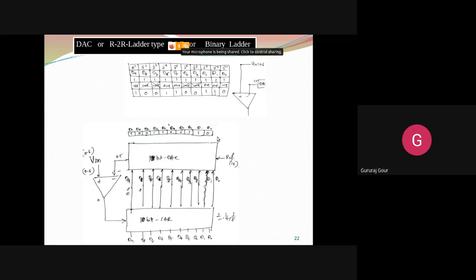Okay. So only this much will be given in the exam, to let you design the ADC and get it converted to analog. So let us see the steps here. So the weights I have written here from left to right for a 10 bit ADC, from D9 to D0. You need to draw the table. Right, D9, D8, D7 and D0, because 10 bit ADC is the question.